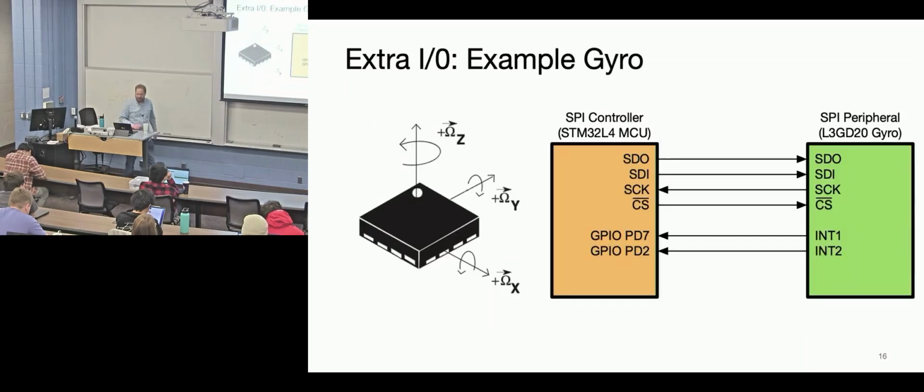We did talk about this one for a little bit already. So this is just an example of, for this particular gyro, that you get interrupts. So it could be interrupt when data is ready. So say you do a conversion, you've told the thing, go take an ADC measurement or a measurement in general. And these things don't often happen instantly. It may need some hold or setup time or some wait time. So it could have a GPIO pin that says, okay, I'll go high when this data is ready, or it could be event-based. So oftentimes you'll see multiple interrupt lines that will encode different amounts of information.